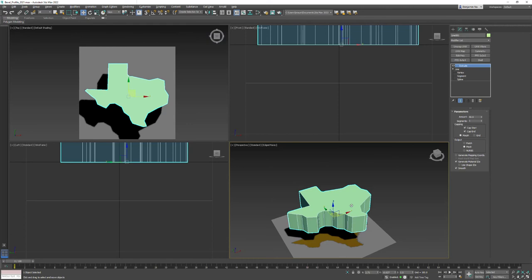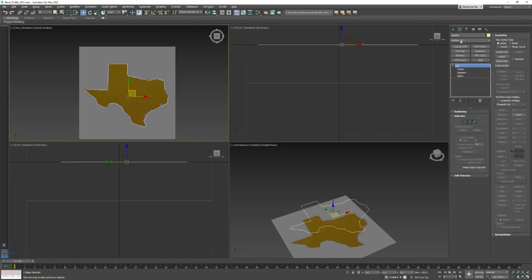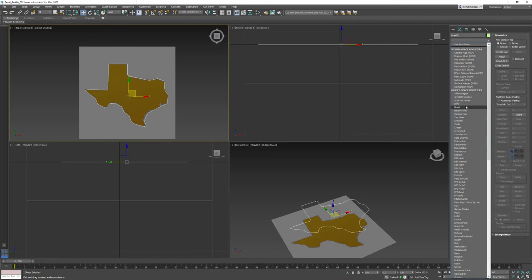The object's orientation, if you go to local, the object's orientation to its local coordinate system is very important when working with something like extrude, because it will always extrude along Z. So if you drew it in the front, the values would be extruding straight up, and you'd have to go back and rework them a little bit. There's another one. There's a bevel.